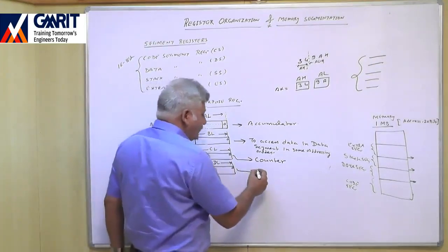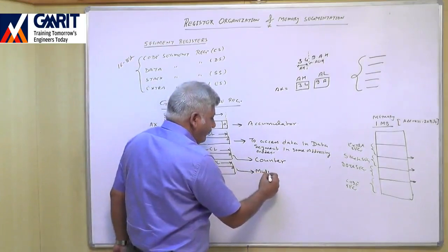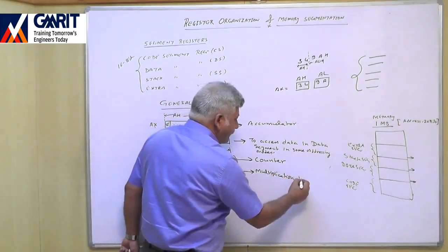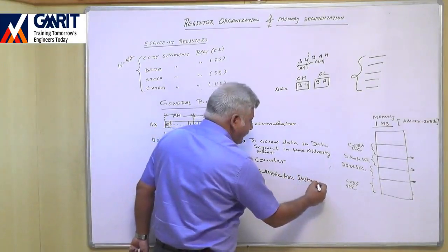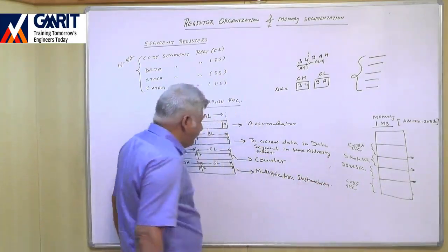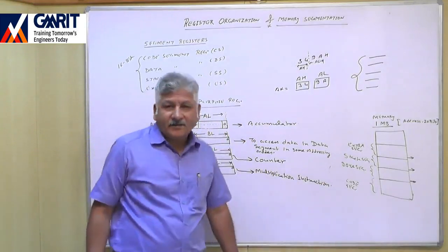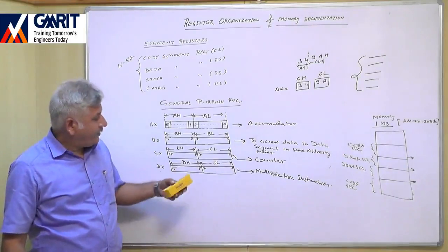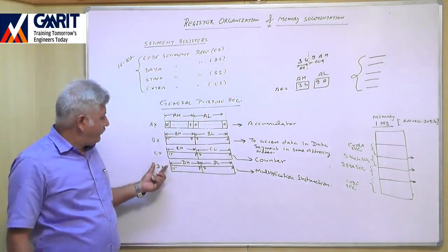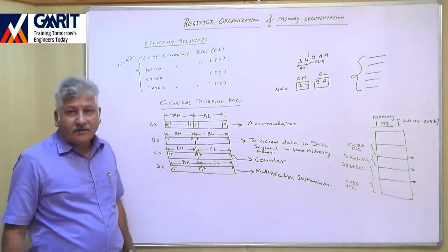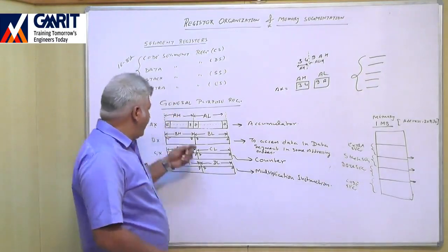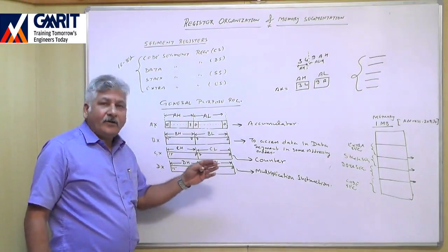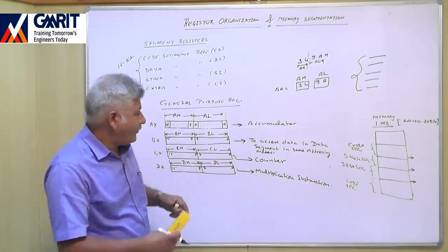So this register is used in the multiplication instruction. When we see the instruction set of multiplication, division and other instructions, at that time we will come to know about the application of this DX register. So these are the general purpose registers, and they serve some special functions also.